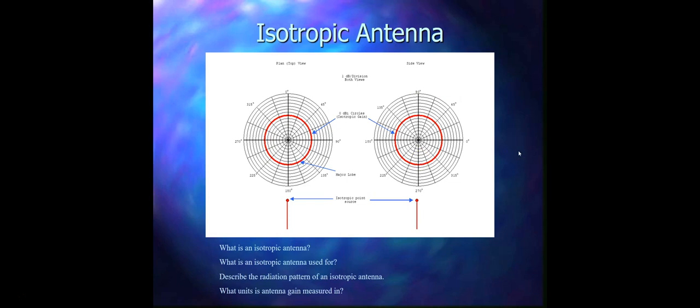And here it is important to note that antenna gain is different from amplifier gain. Antennas do not have a power source that allows the antenna to create additional energy to boost the signal. Antenna gain is actually a measure of the amount of focus that an antenna can apply to the incoming signal relative to one of two reference dispersion patterns. And all antenna gains are specified in dBi.